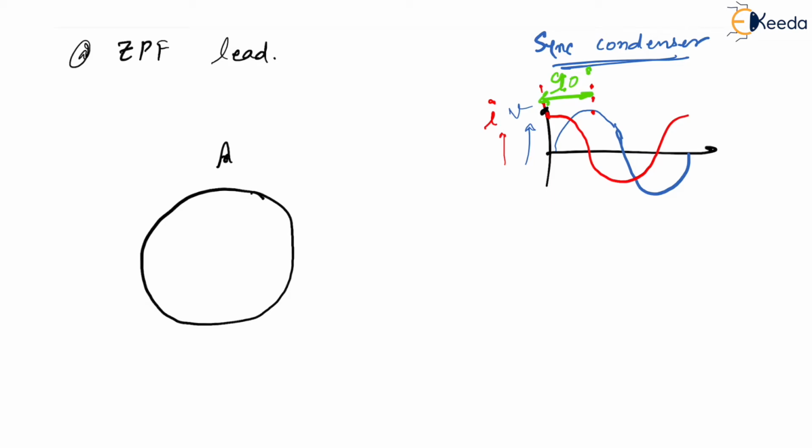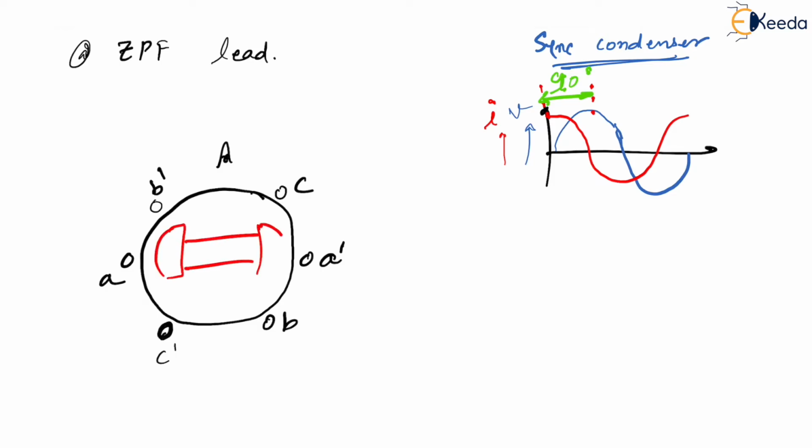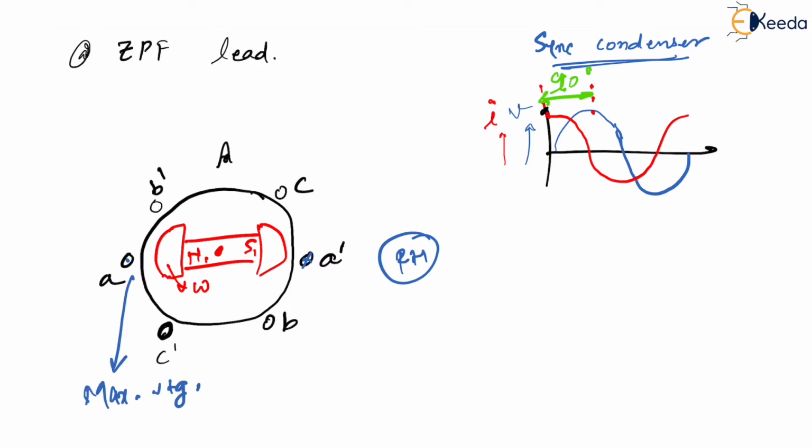This is your stator, correct? Now, inside this I will have a rotor, correct? Yes. And it is rotating, let us say, with the speed of omega now. It is synchronous motor, correct? Running conditions. Now, again, by using right hand rule, what do you get? You get that here you will have dot and here you will have cross. So this is going to be maximum induced voltages. Maximum voltages, let me write down, correct?